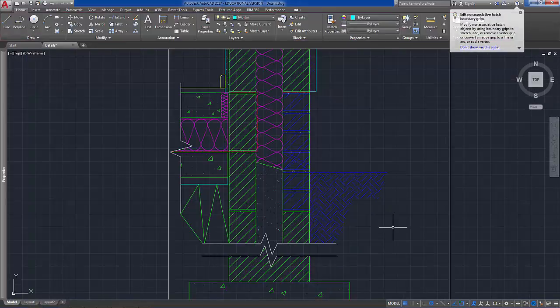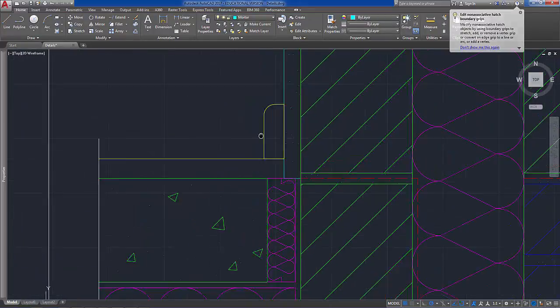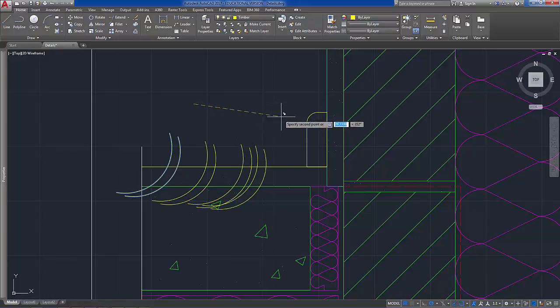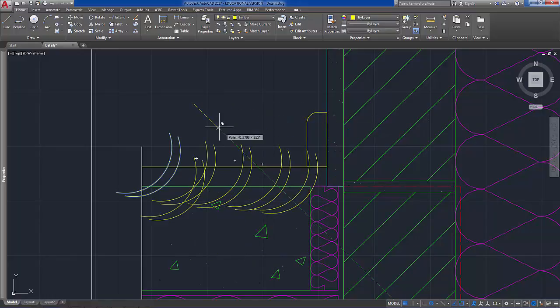The last thing is timber, but depending on which version of AutoCAD you have, sometimes it is actually better to draw some arcs. So let's add an arc or two on the timber layer. And we'll just do this one manually. It's a small area, so it's not going to be too bad. So we'll just copy that a number of times. Doesn't need to be terribly accurate because the pattern will not be always the same. So let's trim that off now.